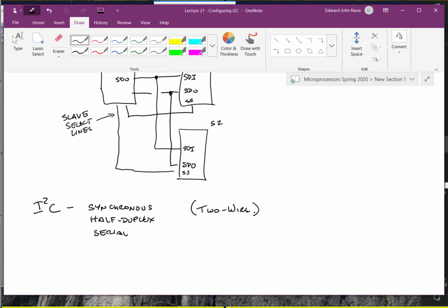we have to transmit addresses. We have all this acknowledgement that's done in the signal, and part of the challenge is now I have all of these signals asserting signals on the line intermittently. They're intermingling who is basically asserting a signal on the line in very, very close proximity in terms of time. And so we see that the SPI and its implementation is considerably simpler for the protocol, but it comes at the expense of having to have more interconnects.